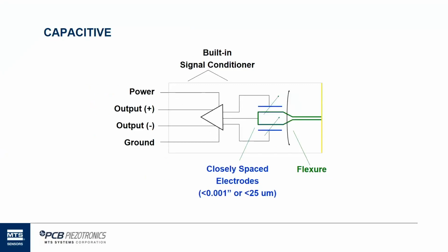We're instead placing that inertial mass between the two blue plates, and those are designed such that they have a specific capacitance in the air gap between the inertial mass and the plates. It's the same concept that when the base of the accelerometer moves up and down, the inertial mass tends to stay in the same place, but rather than the resistance changing in a strain gauge, we see the distance change between the plates.